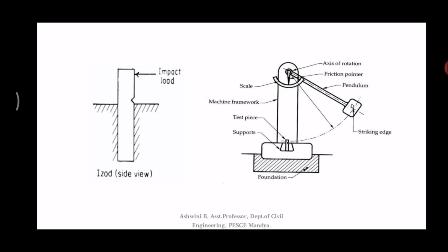Why do we use notch in the impact test? Impact energy is a measure of the work done to fracture a test specimen. When the striker impacts, the specimen will absorb energy until it yields. The test specimen continues to absorb energy and work hardens at the plastic zone at the V notch.